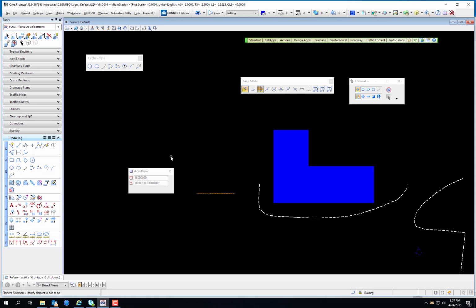This is sort of analogous to what we had done earlier with the Place Line tool. Without Smart Line, without using AccuDraw, we were able to put in a length in the Place Line tool. This allows you that kind of flexibility with all of the tools. When it's in 3D mode, of course, it will allow you to additionally specify a Z coordinate.